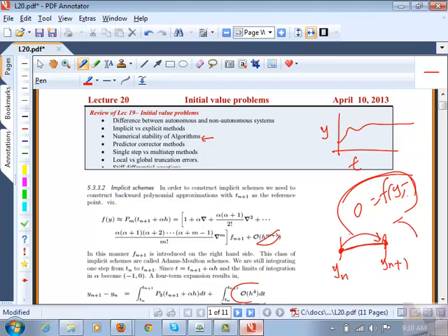And so if you had some initial condition, and this is something that every one of you will experience if you are using COMSOL at some stage, or any simulator. In the iterative process to reach a steady state, what do we call the initial value that we give? An initial guess. An initial guess to the problem, and Newton's method gets rid of that error in the initial guess and gets you the solution.